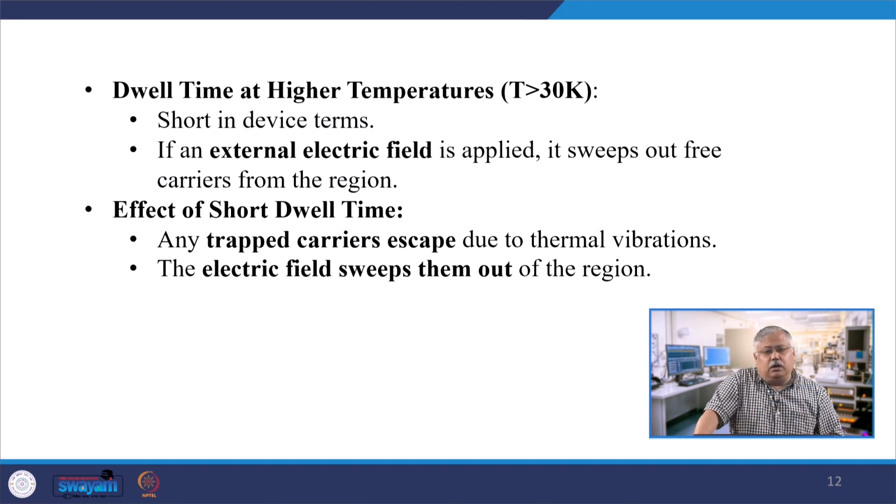then this external electric field will sweep out the trap. So, it is not only important that the temperature rises and therefore releases electrons from the traps, but since it is a low energy state, if there is no sufficient external electric field, these electrons will never be dragged or drifted away from their localized position, and then they will again fall back to the low energy state, which is the trap itself.